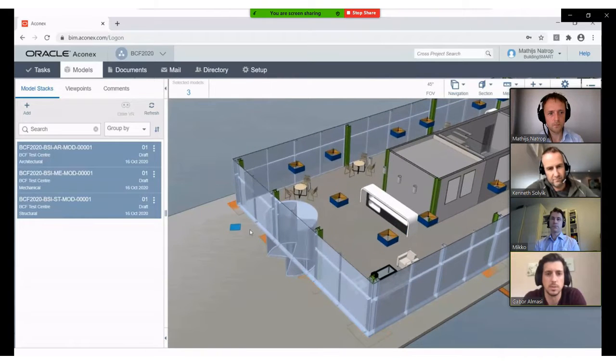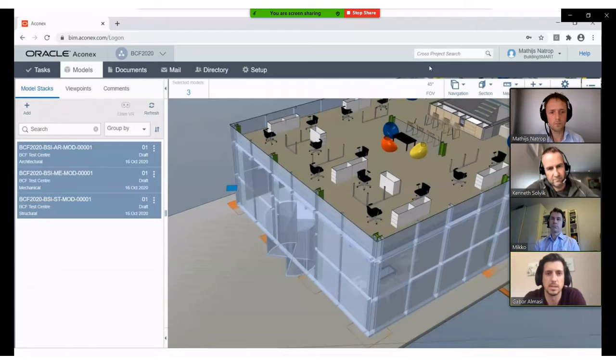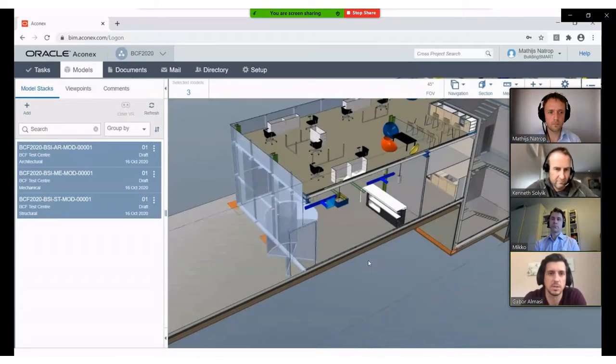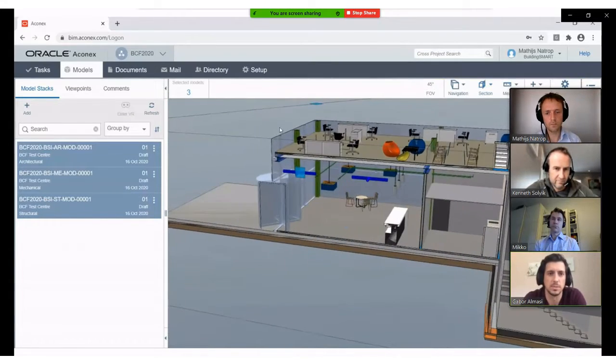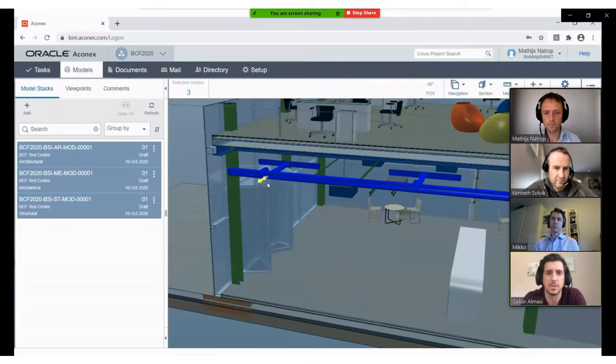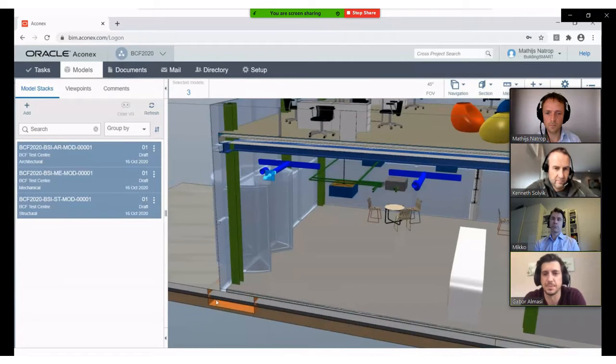Sure. So as the building's facade is made of glass, this area should be transparent as well, and is in the middle of the entrance. So I'd like to avoid any columns which would obstruct the view. So perhaps a self-supporting glass wall would do just fine. Okay.